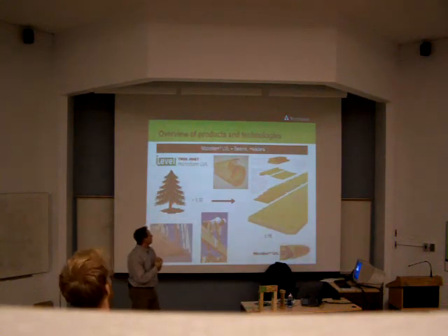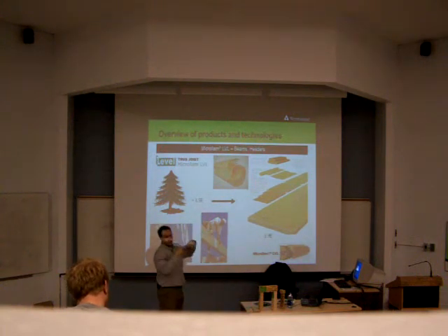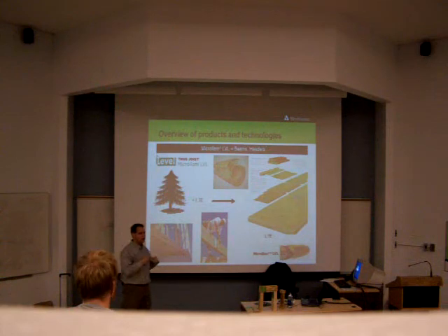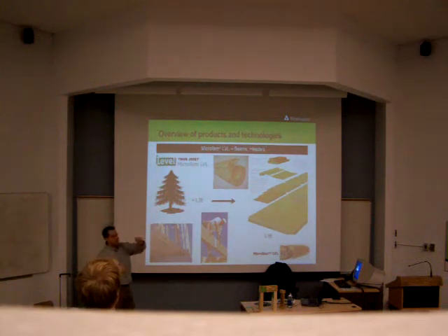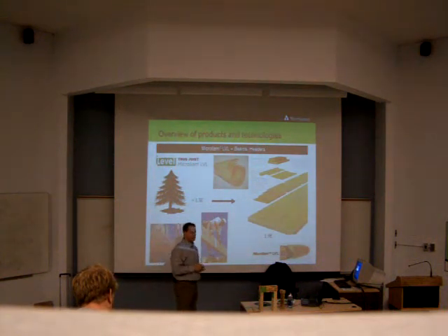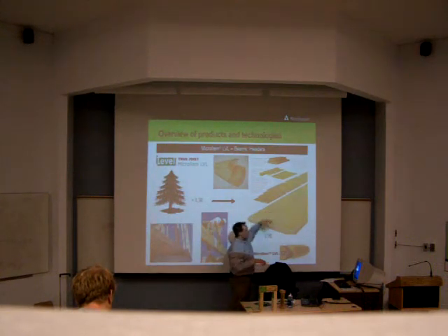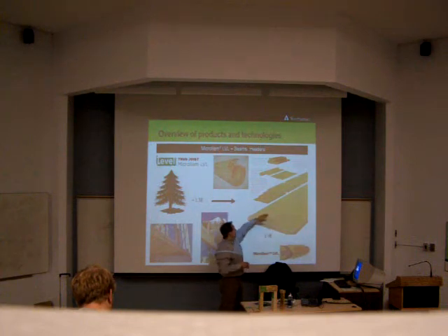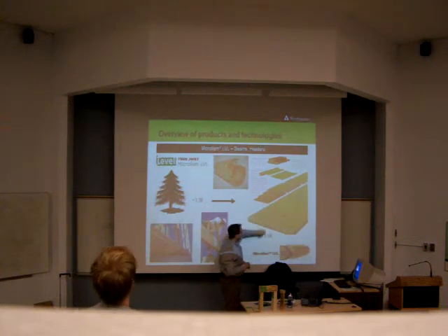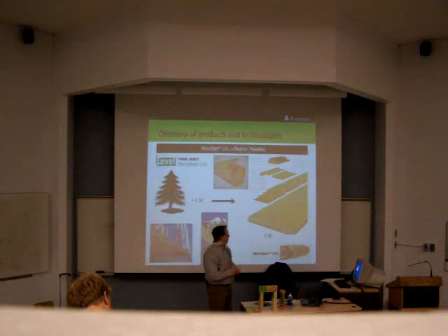Micro-lam, the way LVL is made, is basically we take a billet, you peel it, like a roll of toilet paper, you peel the log into veneers. It's real thin veneers, just like plywood. And then each of those veneers is graded, electronically graded. It's a real scientific process. And then we can basically overlap those veneers in whatever strategic way, putting different grades in different places in the billet, and it's pressed together with hot plates, top and bottom. And out comes LVL. Okay.